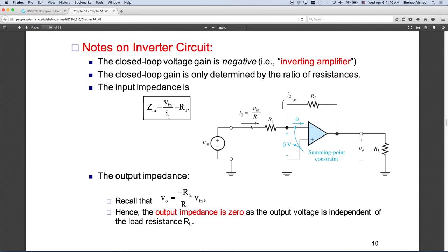What is the impedance that it is seeing? It is seeing an impedance equal to V input over I1, over the current that's flowing. Right? V input is your sensor voltage divided by the sensor current. That's the input impedance that the sensor is seeing. As if there's a black box, like there's a Thevenin equivalent circuit with just an impedance. What is that impedance equal to? Equal to the voltage divided by the current. Right? You want that impedance to be high so that the current is small. You don't want high current to be consumed from your sensor. So typically amplifiers will have a large input impedance.